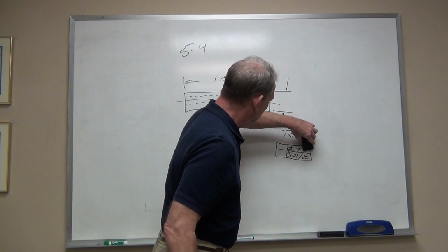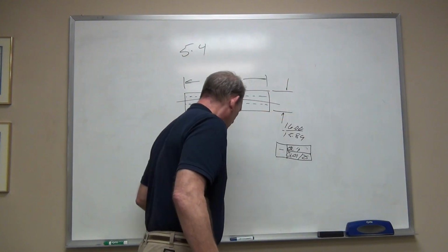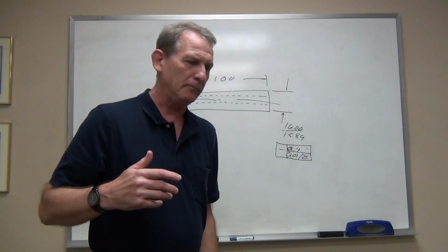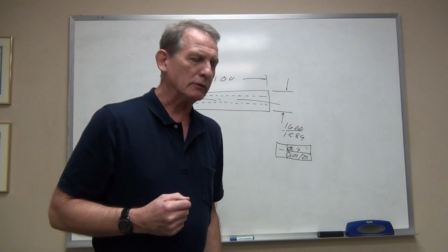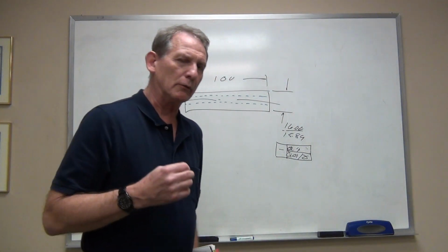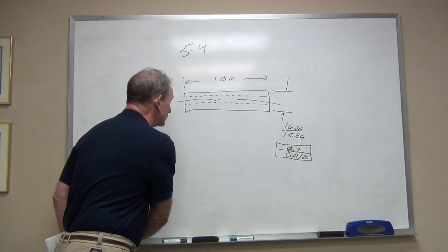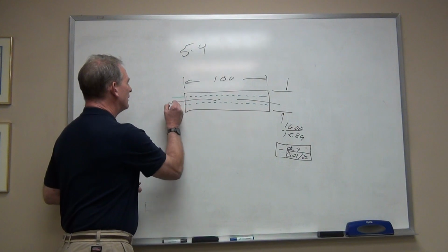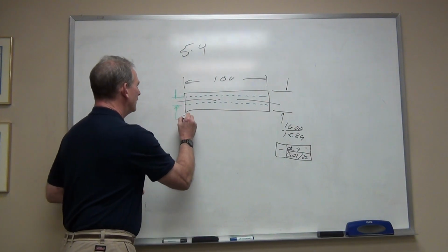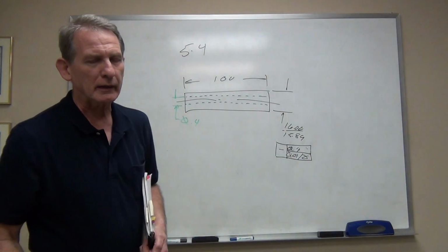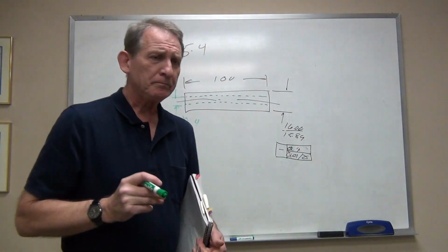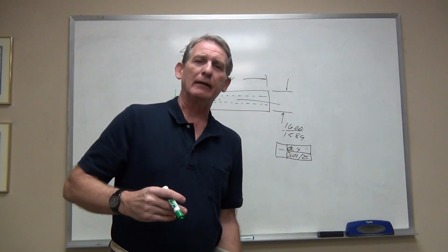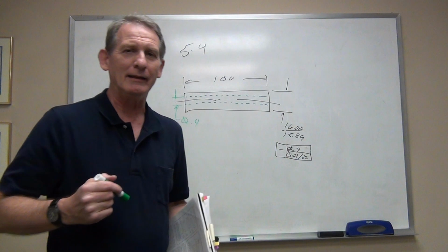Okay, and we could leave it at that if we wanted to, but the engineer may be concerned that that fairly large tolerance may result in a condition that he really doesn't want. What he's probably most concerned about here is that once you have established that 0.4 diametral tolerance zone, that derived median element, that center line, can do anything it wants within that space.